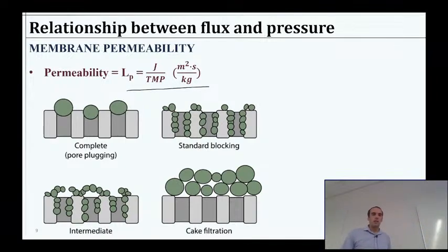Okay, so a little bit deeper here, we can talk about membrane permeability. This is another associated concept. I'm going to keep this pretty basic. We could go into depth. There's quite a lot of physics and fluid dynamics involved with really charting what's going on with membranes at the pore level. But we could talk about a permeability term, LP, that would just relate also the flux compared to the pressure, right? So we could say permeability is flux over transmembrane pressure.